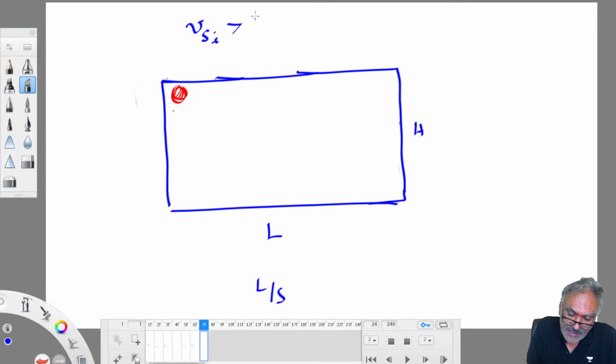We adjust that V0 slightly more than settling velocity. We see that V0 is less than Vs. That means Vs is more than V0. First we work out Vs and we see that Vs is more than V0, and we design this, or at least equal to V0. We design the sedimentation tank.